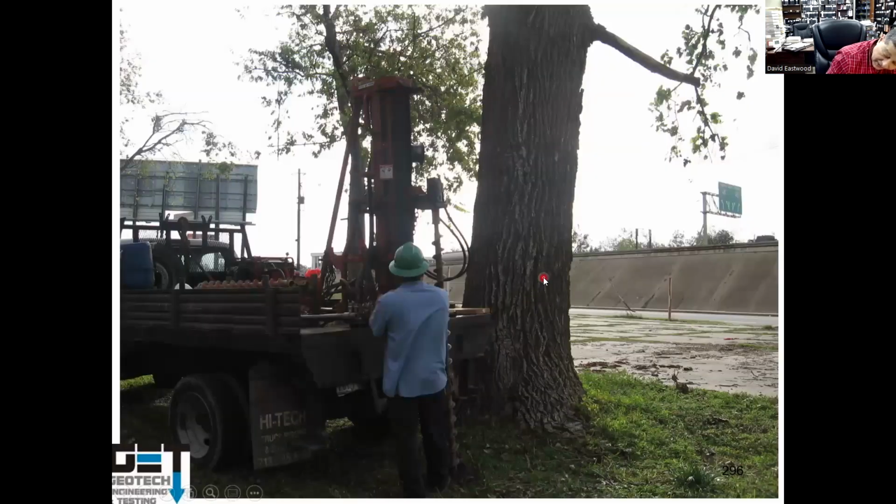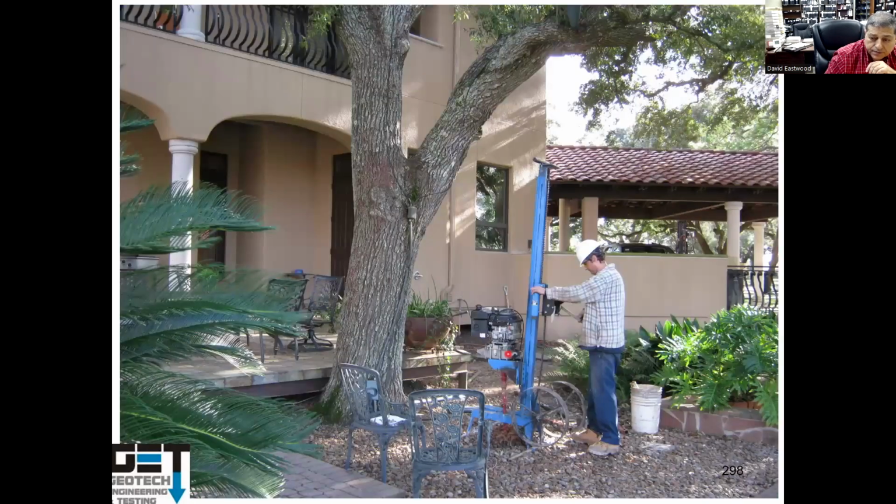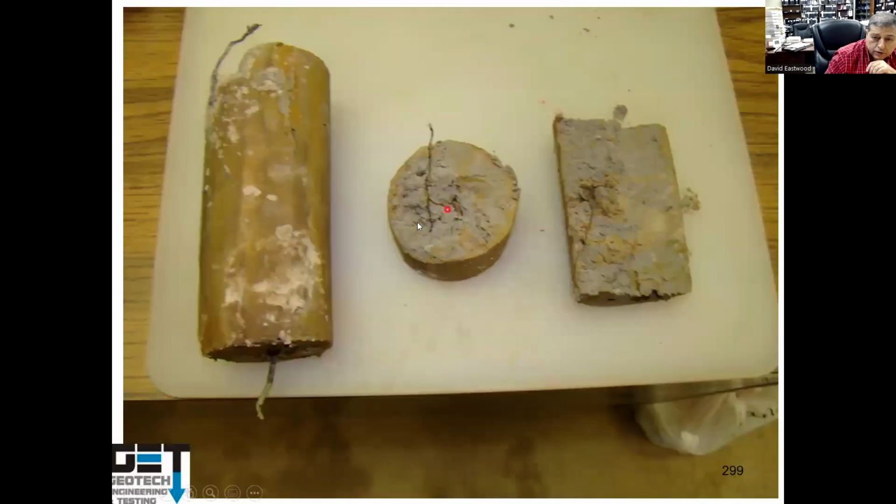We'll also do geotechnical sampling to see what kind of soils you have for buildings that are cracked up. We do the borings next to the biggest tree on the properties. Trees tell us where your foundation for a building should be, because of the presence of root fibers. So we do the borings. This is a portable rig. You look for root fibers.